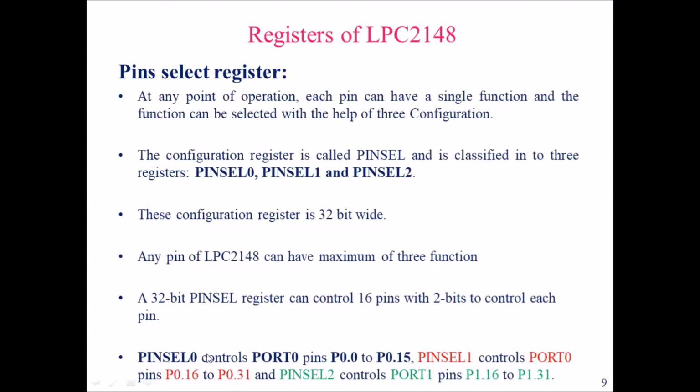So pin select 0, the first pin select register, will control only port 0 pins, from port 0.0, the zeroth pin, to port 0.15, the 15th pin. Do you understand? So pin select 0 controls port 0 pins from the 0th pin to the 15th pin.